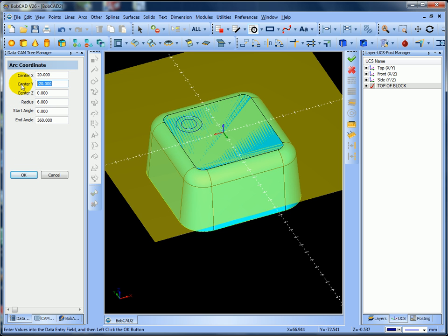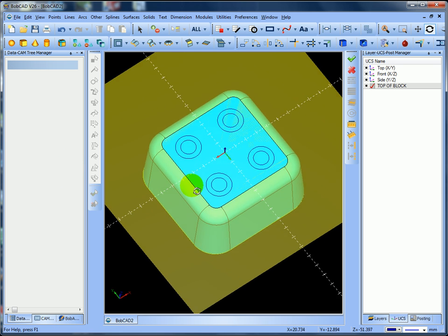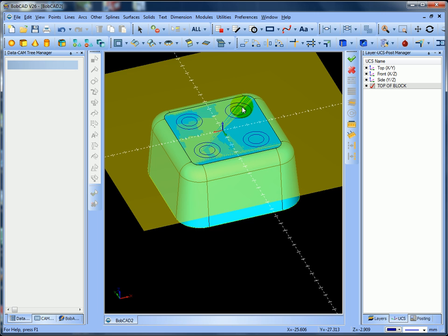And then I'm going to put that to 20, and that would be the new position. I'm going to accept that's OK and change the radius on top and select OK. I'm going to change that to -20. That's my new position. I'm happy with that, and then I'm going to put a 6, select OK, and then Y. Sorry, Y. That's the new position. I'm happy with that. Select OK, and I'll change the radius and cancel. So what we've done now is we've created some new geometry on there for the holes we want to put in there.